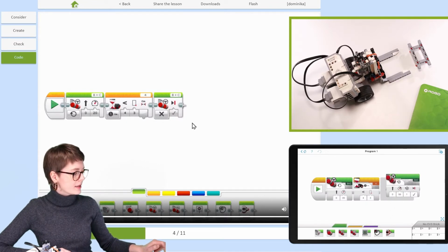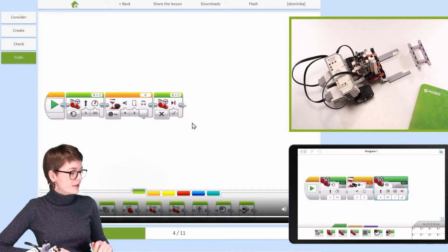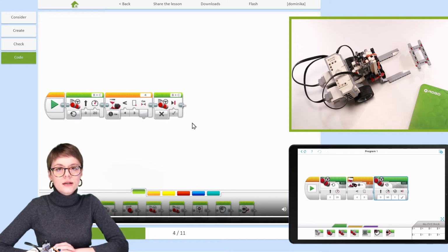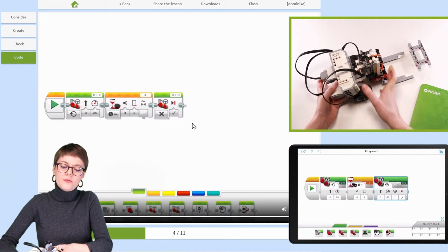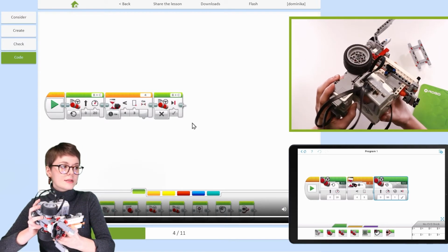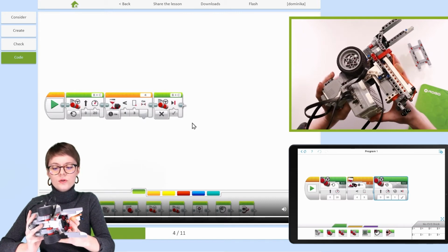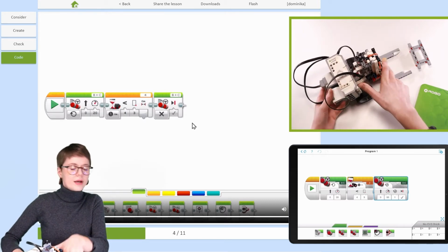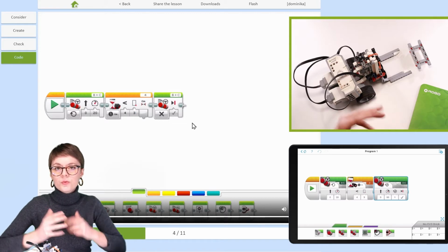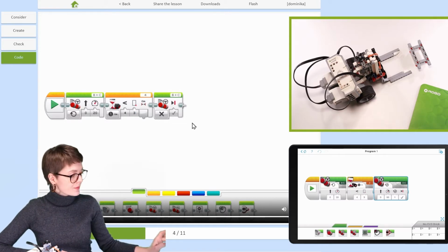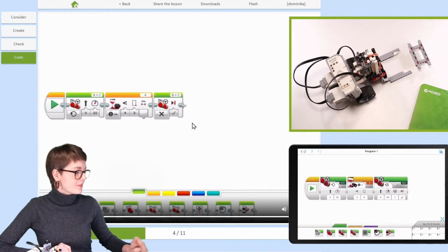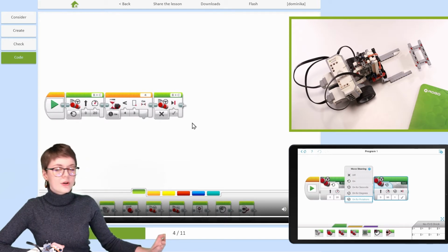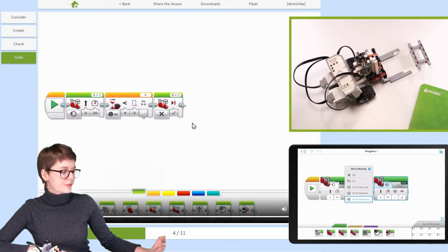It's right here, okay. And notice that once again the ports must remain the same. Now for me, both of those motors are connected to B and C ports, so I don't need to change anything right here. But remember that if your motors are connected to different ports, you also need to change them in this block. Okay, now I need to change the mode, so of course I will just turn those 2 motors off.